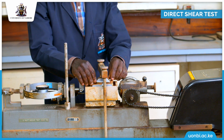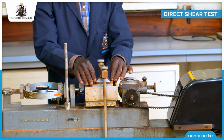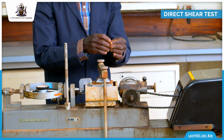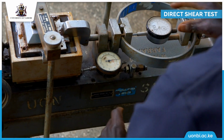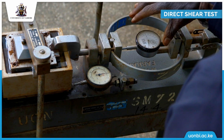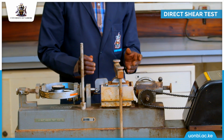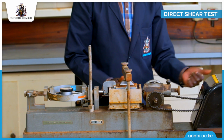These screws were only to assist us to be able to hold the two halves together. So I want to remove the screws before I start the machine. I also have to ensure that the dial gauge, the pointer is at 0, 0. After ensuring that everything is okay and the screws have been removed, then the next thing is to start the machine.